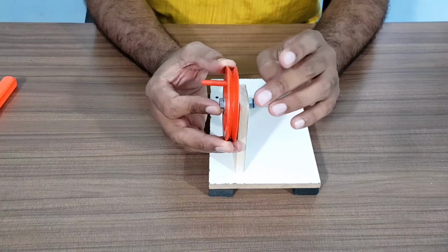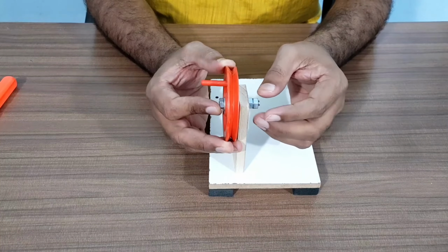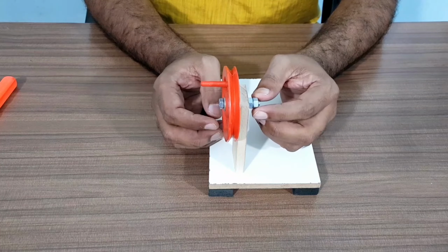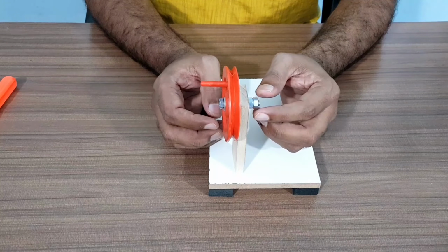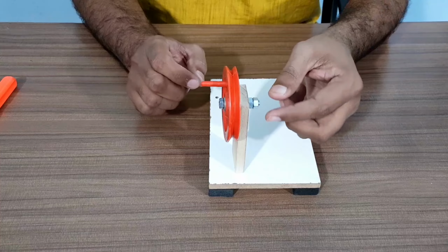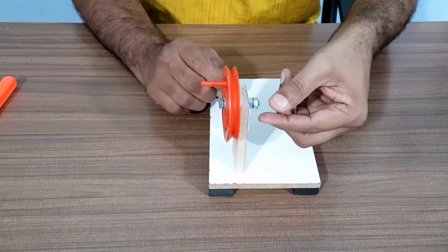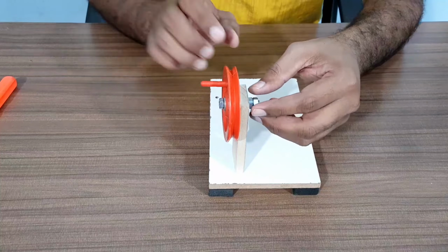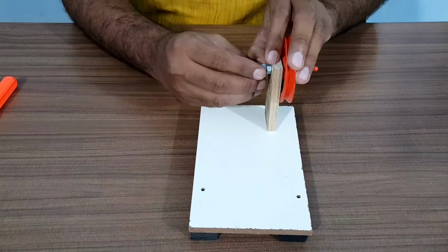Now here is how to make a lock nut. If you see, if I am moving this one nut, it is pushing another nut as well. Here what you have to do: the outer nut you have to move clockwise and the inner nut you have to move anti-clockwise. So I will use this angle.